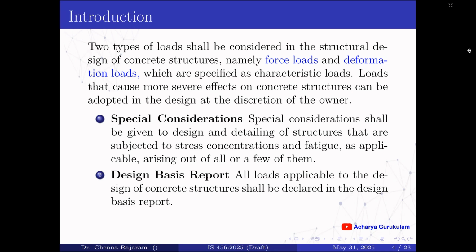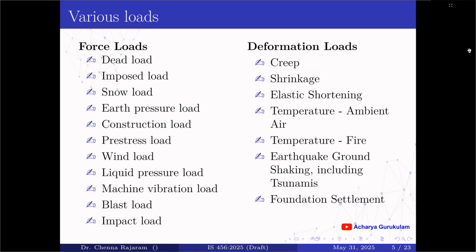All loads applicable to the design of concrete structures shall be declared in the design basis report. The force loads and deformation loads are categorized here. For force loads: dead loads, imposed loads, snow loads, earth pressure loads, construction loads, pre-stress loads, wind loads, liquid pressure loads, machine vibration loads, blast loads, and impact loads. All these loads come under force loads.